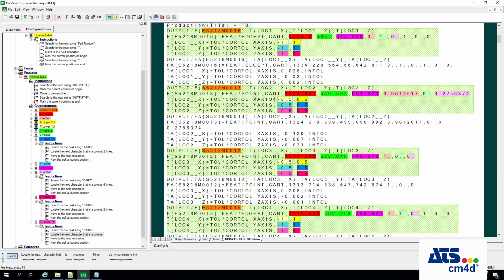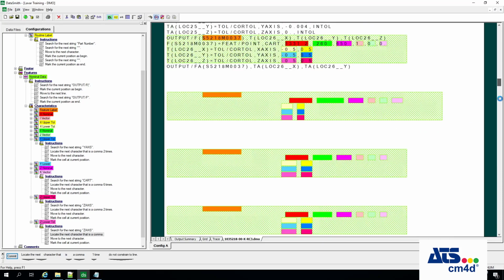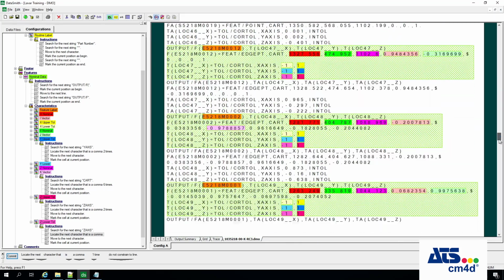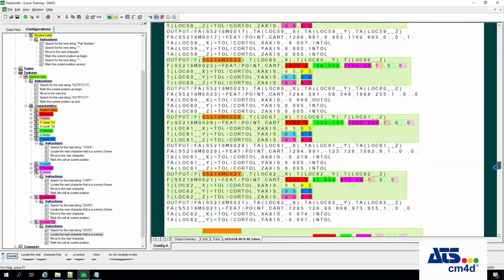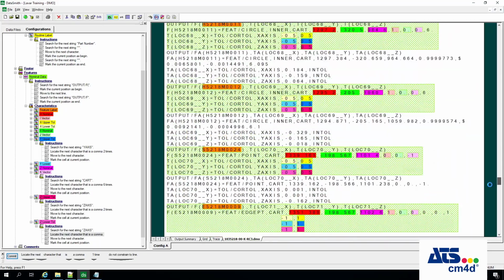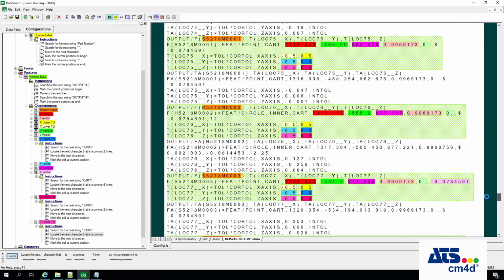So with that being done, we're grabbing the X, Y, and Z nominal information from this file that's available. Now there might be cases for other files where you had other dimensions like position, or if you have a hole point, it might have a diameter nominal, or if you have a slot point, length and width. In those particular cases, we can add definitions to this in order to pick up that information. So let's see if we have something like that in here.